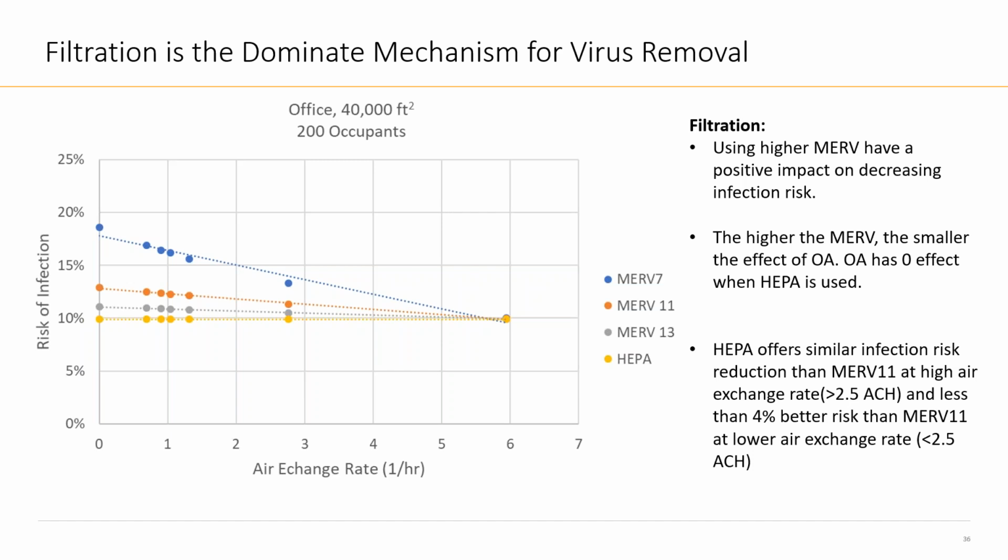And then you take what we know about the MERV efficiency for each category, and you calculate an average size distribution, and then you incorporate it in this model and you look. For me, honestly, this was a little bit surprising because, if we say, okay, let's all do MERV 13 and get done with it, or MERV 14 or HEPA, but it comes at a cost. If today your system cannot move, because usually if you have high MERV, high pressure drop, it's not always the case, but usually it is.